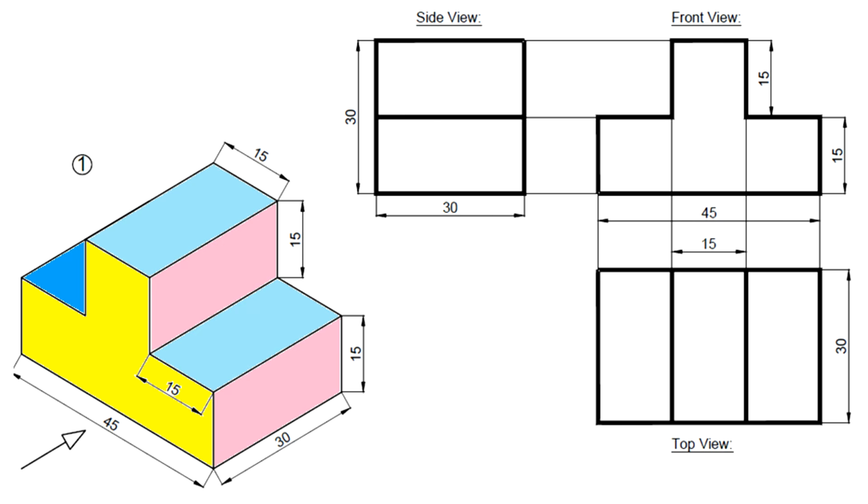So this red color surface in the top view will appear like this. It will not appear as a surface actually, it will appear like a line, and this red color surface appears like a line in the top view. So I will first draw the principal surface, that is 15 by 30. I can make some gap between the front view and the top view.